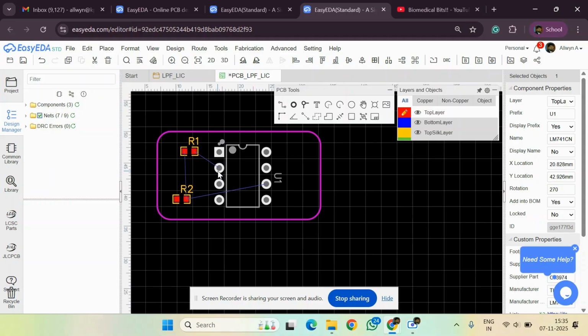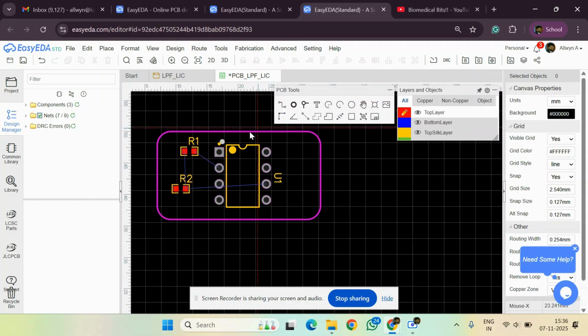So this is usually pin number 2. So you'll have your input somewhere here, right? And your output is here, right? So now what we have to do is create the connection here also. There we created the schematic connection. Here we will be making the PCB connection, right? So again, you choose wire, connect.